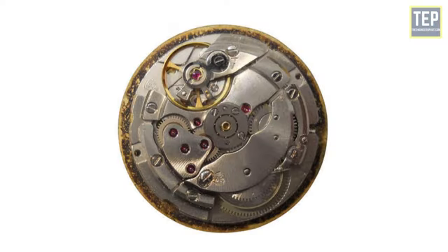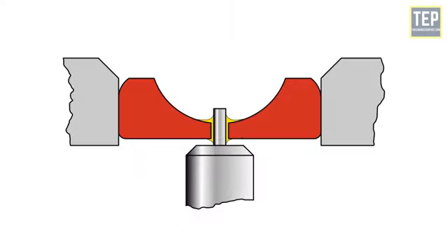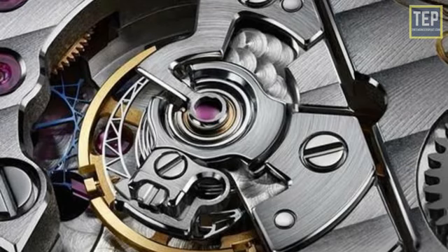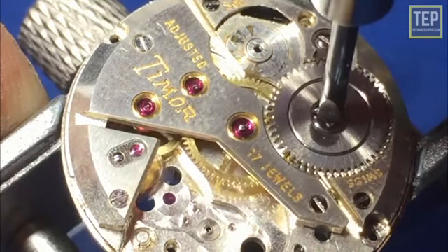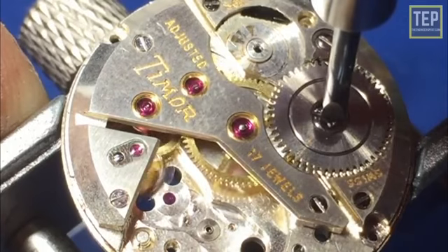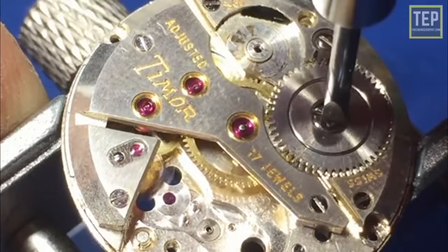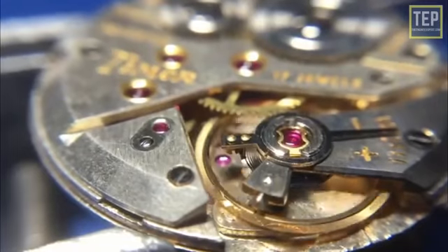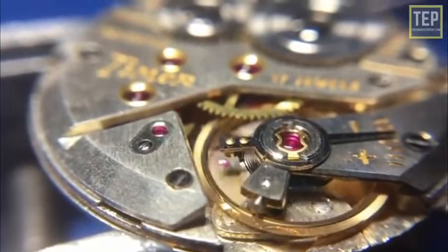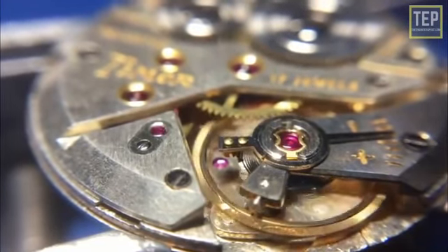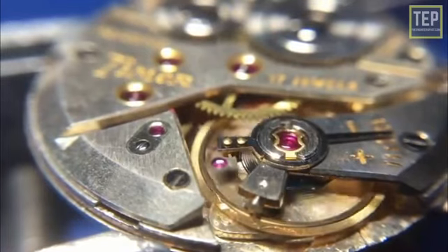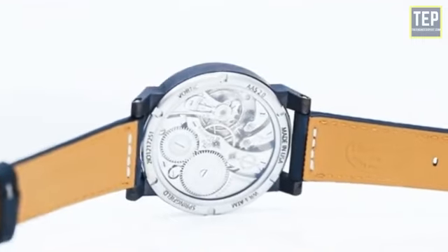A jewel bearing is a plain bearing in which a metal spindle turns in a jewel-lined pivot hole. The hole is typically shaped like a torus and is slightly larger than the shaft diameter. The jewels are typically made from the mineral corundum, usually either synthetic sapphire or synthetic ruby. Jewel bearings are used in a range of industry applications and in precision instruments, where low friction, long life, and dimensional accuracy are important. Their largest use is in mechanical watches.